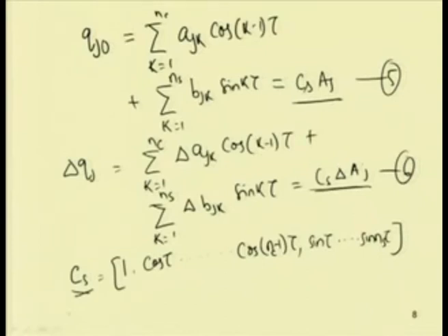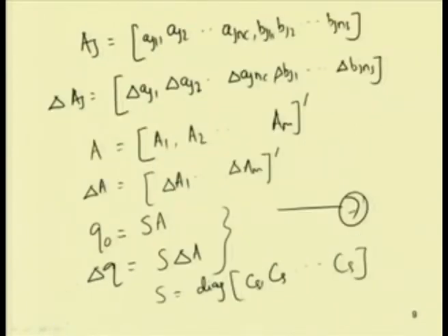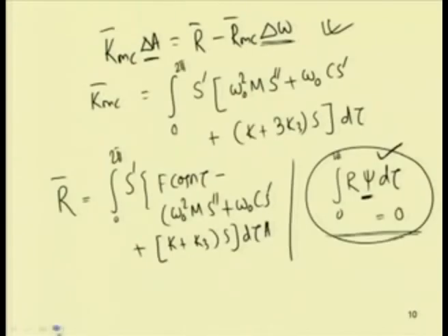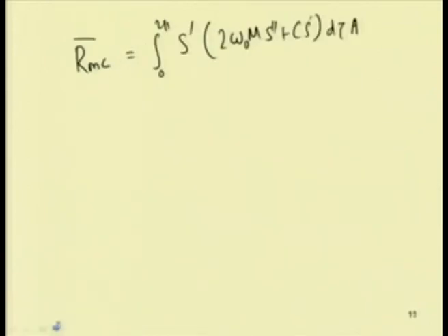So, now there are many modifications of this incremental harmonic balance method also. One such modification is carried out by Cheung et al., where they have taken the arc length in this incremental method and found the solution.